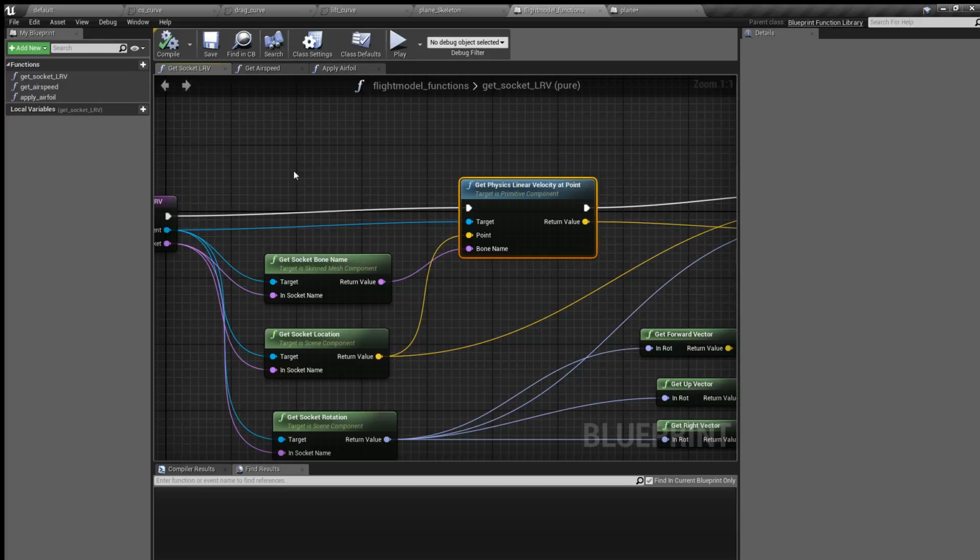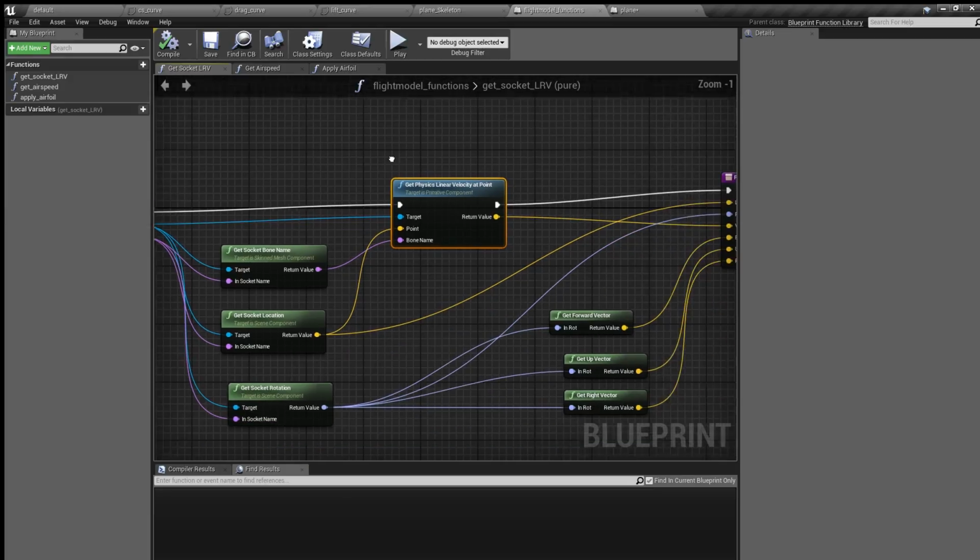So in case the object is rotating, in case of our simulator the airplane is turning, the velocities on different parts of the aircraft will differ. In case of, for example, a turn, the velocity of the outer wing will be higher than the velocity of the inner wing, which means more drag, which means the airplane will resist the rotation. In other words, it will be self-stabilizing, just like a real airplane.